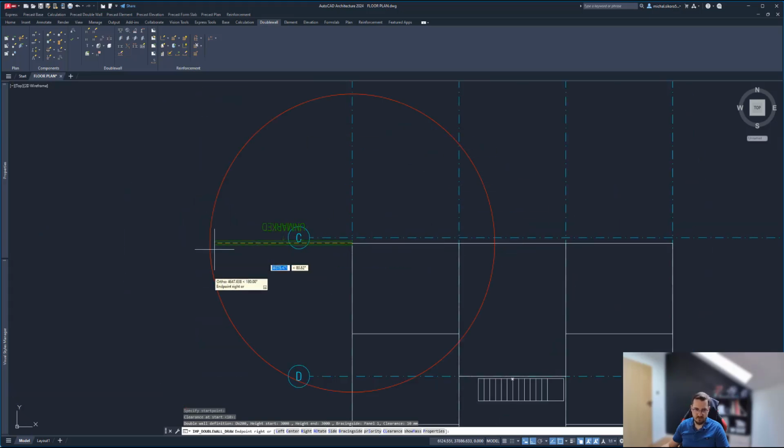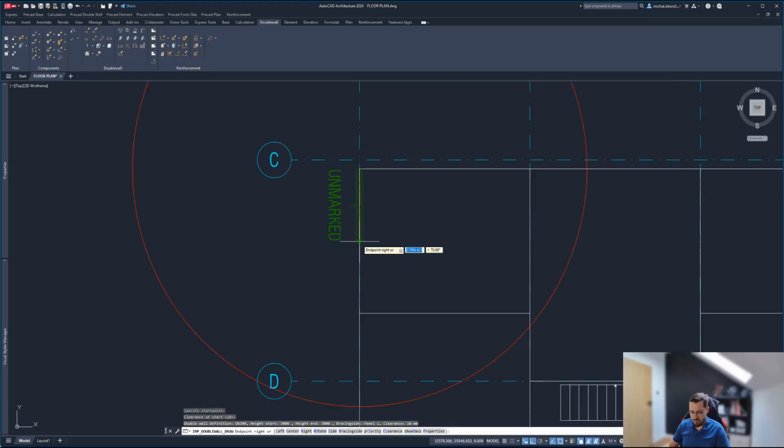So what happened here, once I zoom that out, from the point that I clicked as the origin point of the wall, you see this large red circle. This basically gives you an immediate idea of the allowed size of the element. This is the max size of the element that you can get while still within the acceptable range that's set in your project settings. So basically you can produce that and lift that element out of your table or form. If we exceed that, the software won't stop us, but the element will be marked red, meaning it's too big and needs to be split at a later date. So let me play around with that a bit for you.